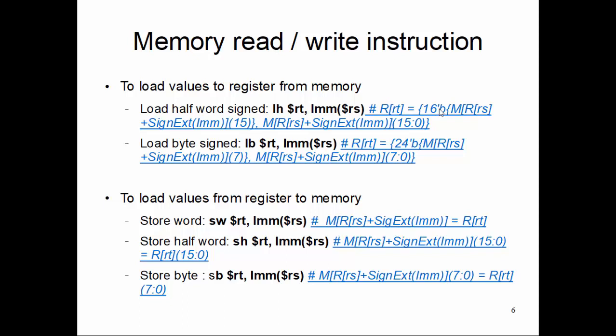In your programming, when you load some data from the memory, only at that point are you worried about the signedness or unsignedness of a certain sequence of bits. When you store, you just store that number of bits, and you let the usage decide how to treat that 8-bit or 16-bit as an unsigned or signed value. Depends really on the program. So that's why the store commands, especially store half and store byte, do not have a corresponding unsigned part. It's just pure bit pattern storage.